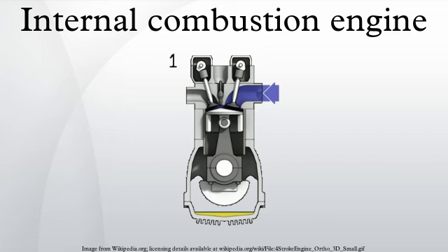On the PV diagram, 1 to 2, intake suction stroke. 2 to 3, isentropic compression stroke. 3 to 4, heat addition stroke. 4 to 5, exhaust stroke. 5 to 2, heat rejection. The distance between points 1 to 2 is the stroke of the engine. By dividing V2 by V1, we get r, where r is called the compression ratio of the engine.